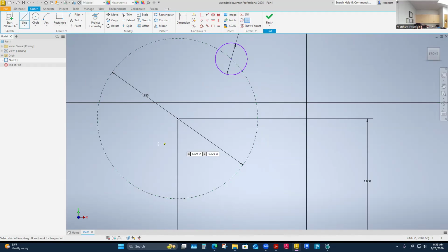It's kind of interesting. Here's my line, and from a line, it does have an automatic grip that shows up. The only reason mine's still, now it's bound in the circle for sure, and it's also bound horizontal just because I made sure that constraint showed up when I snapped it. But I need it to be in the center of the circle. So essentially this is a diameter. Even if I just pick the line, it'll be correct. If I pick the midpoint of the line, maybe it's a little more correct, but that's all I did. I just use it as construction.